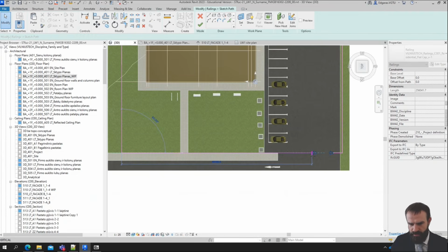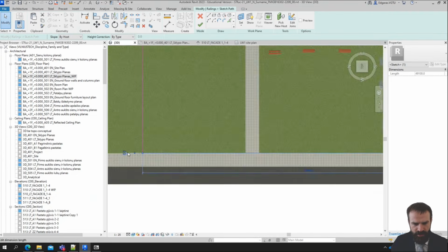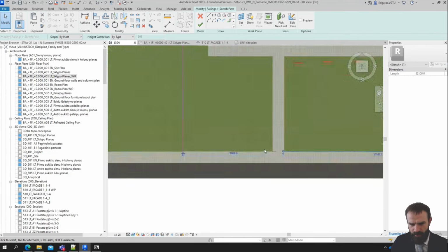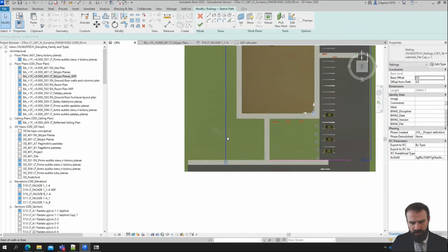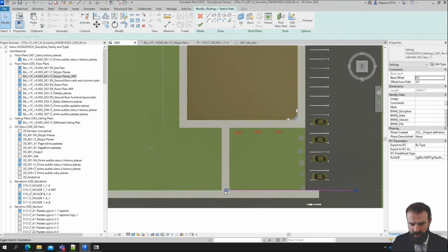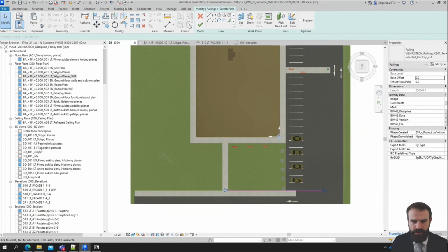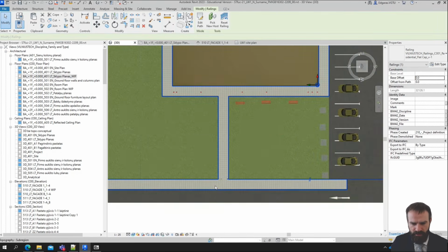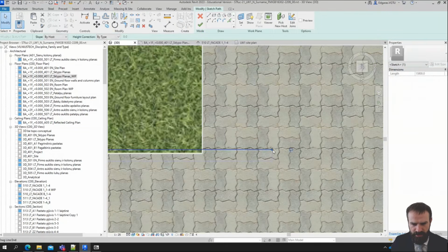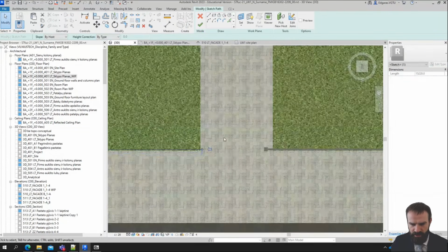And I just drag, so this will be the entrance for the cars, and this will be the entrance for people. And all other, I select the trim tool and just delete. So it means the line should be also continuous, cannot be made from different parts. So for this part also I can move the line here.